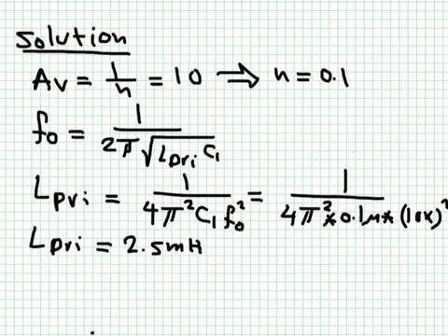The only difficulty with this Armstrong oscillator is that it requires a transformer. And using a transformer is not usually a desired thing in oscillators. So usually I would say the Colpitts is the one that's most commonly used, because it's much easier to control the value of capacitances rather than to control the value of inductances, and also because it does not require a transformer.